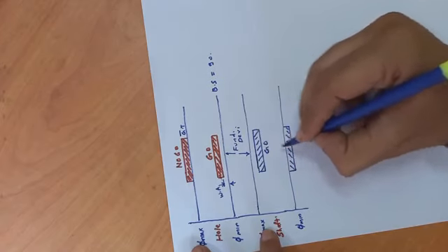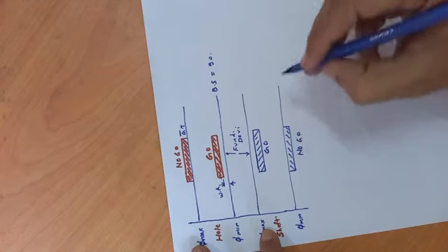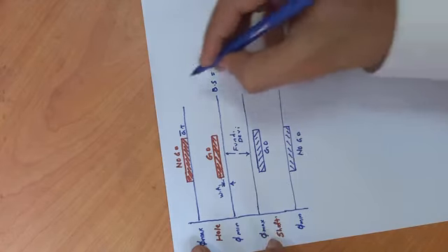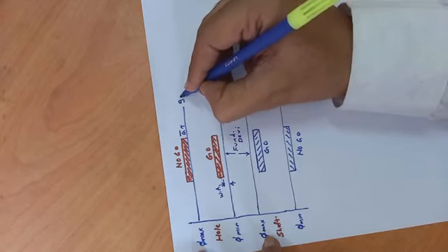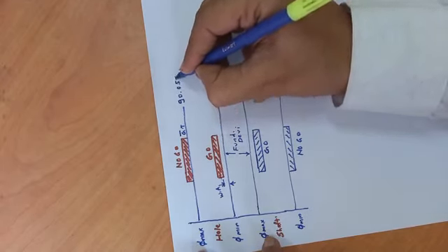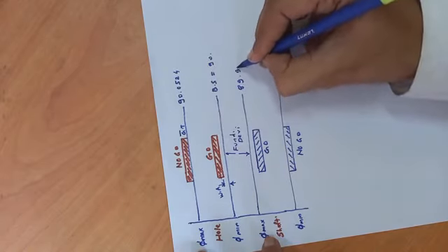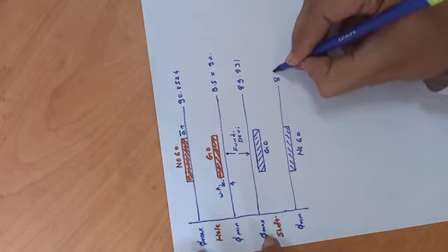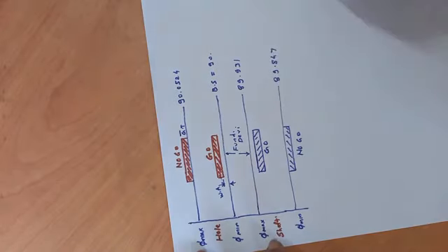This is go gauge and this is the value for no go gauge for shaft. The phi maximum for hole is 90.0524. It is 89.931 and this is 89.847. All these values we have calculated.